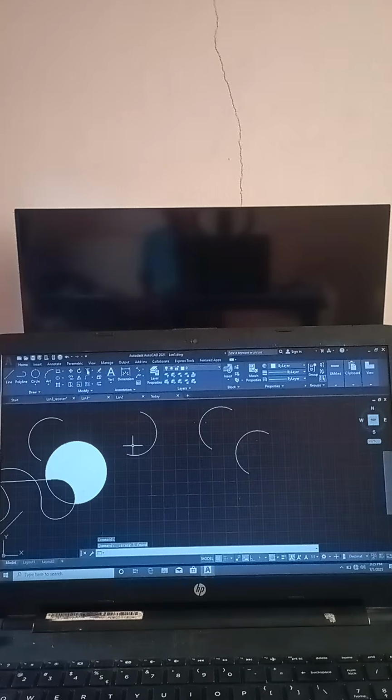Then you have trim. How do you trim? For instance, you have stuff like this. Now I want to trim an object. I select trim. Sorry, the system is a bit slow. I click on trim or TR, enter. It's slow. Sorry. I click on it again. All right, it's activated. If anything I touch has a boundary, it goes. You can see it now, trim that area.